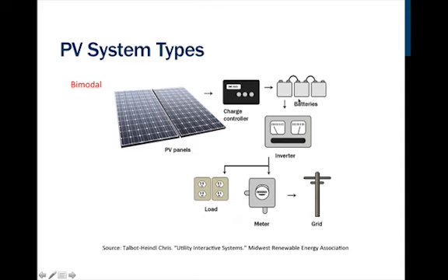The battery pack is going to be sized for our needs during the average power outage and what we need to run during that average power outage. Maybe it might be a well pump or refrigeration or servers or lighting. Whatever you need to run during the power outage, the critical loads will run off this battery pack through the inverter to the load. Once the grid comes back up again, the inverter monitors for 5 minutes. If everything's okay, it relinks to the grid and we're up and running. We don't even know there's been a switchover. So this is a very reliable system out there.